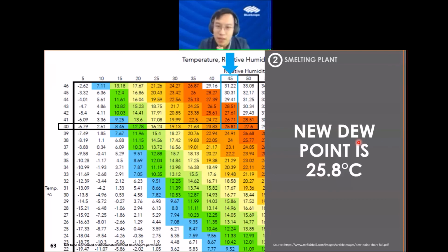So it's possible to actually measure it using a device that measures dry bulb temperature and wet bulb temperature, and from there you can measure the relative humidity together with what they call the psychrometric chart, right? So that is a very old school and very mechanical way where engineers normally refer back to the chart, right?